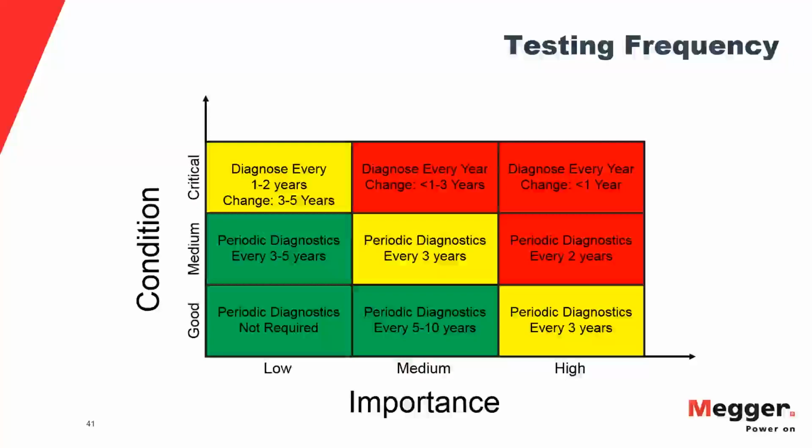Yeah, just to add to that, just to explain that the IEC standard is very strict and very detailed in terms of the measurement circuits that you're using and how these signals are processed and how the signals have to be integrated. So pretty much like partial discharge, these signals can occur over a very wide frequency band that stretches from some lower kilohertz to, as Jason said, the megahertz.